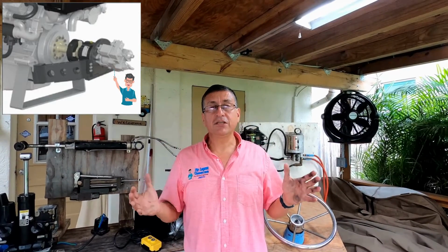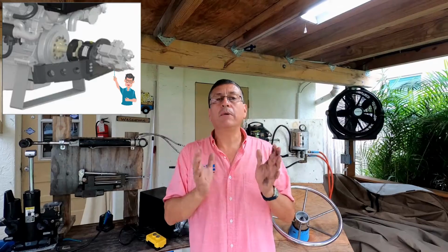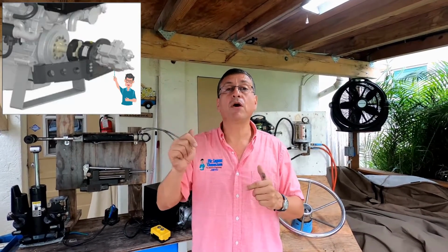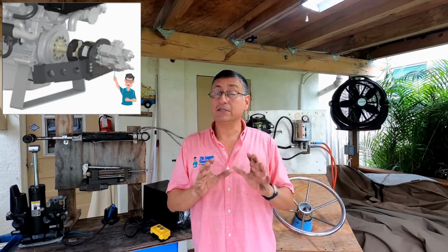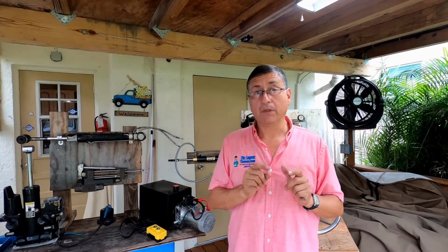In other words, the hydraulic system in boats has redundancy. What is the meaning of that? Normally, when the main engines are running, the PTO supplies the hydraulic fluid for the hydraulic systems. When the engines and generators are off, there are electric motors that move the pumps and the hydraulic systems work properly. All right, this is very, very important.